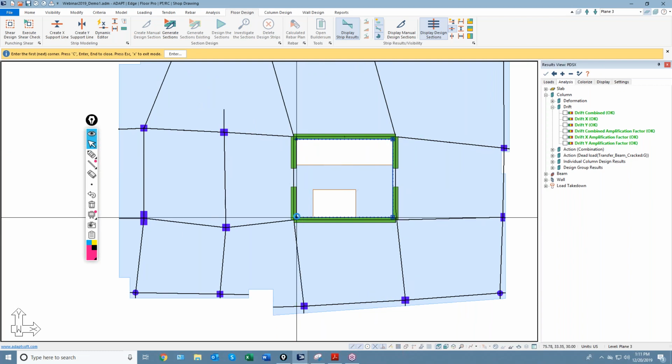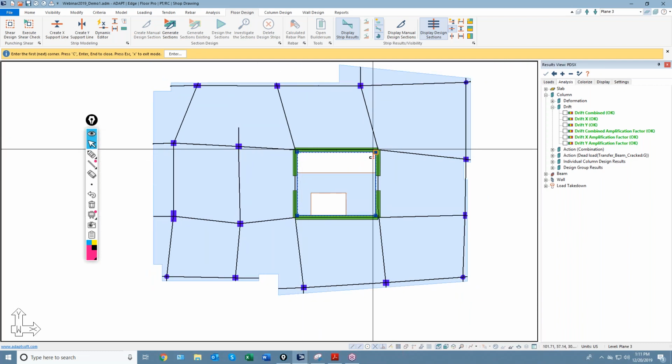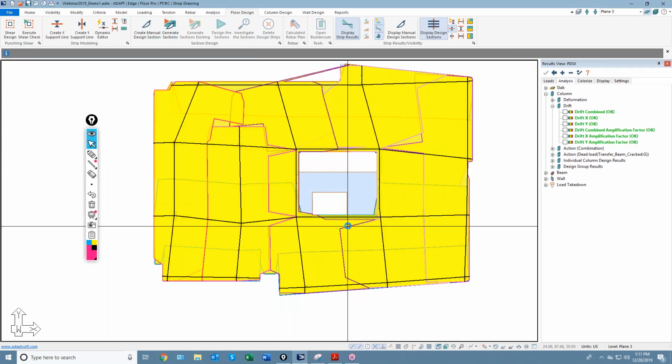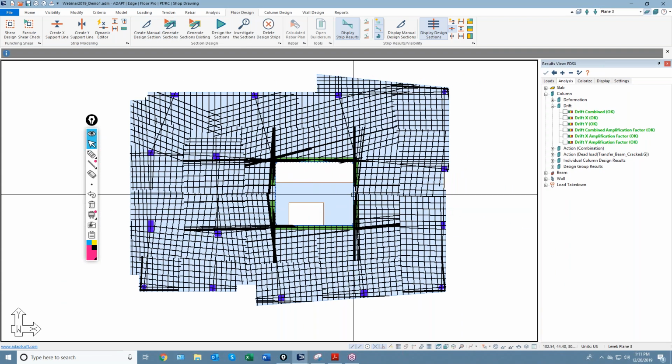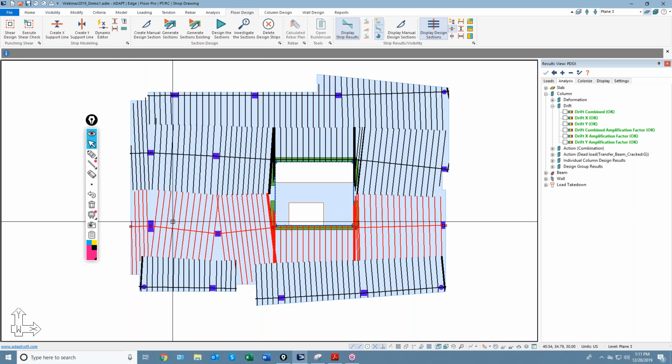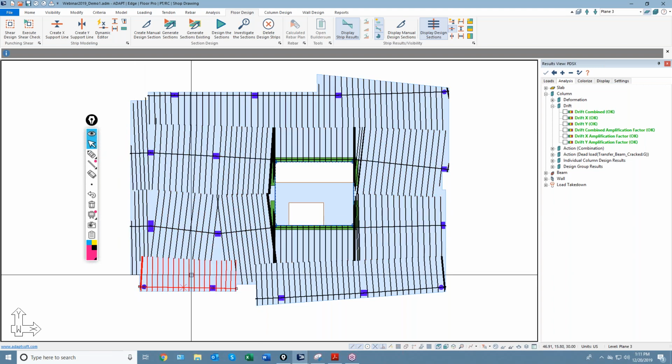Okay, and the Y splitters are interpreted by the Y support lines, the X splitters are interpreted by the X support lines, and when I generate my strips, this is what I end with. And if I isolate those, you can see there's very little correction needed to be made in this case. I mean, these are nice, usable support lines without having to go back and iterate through multiple corrections using splitters. So the only splitters we have are really to bound out this opening in this core area.